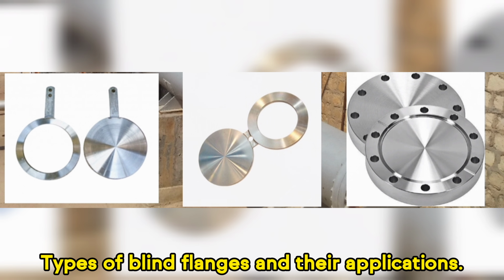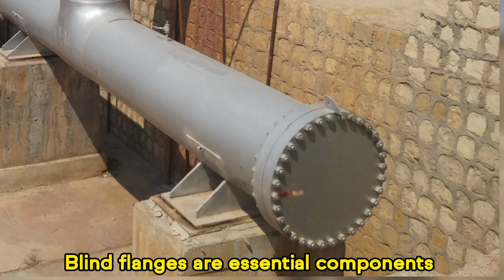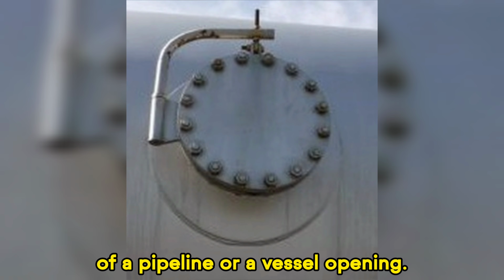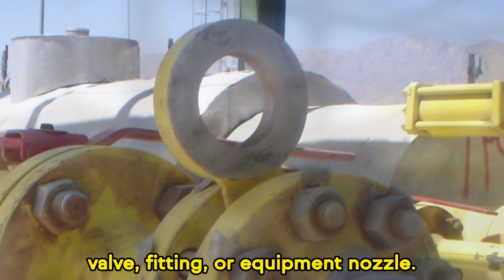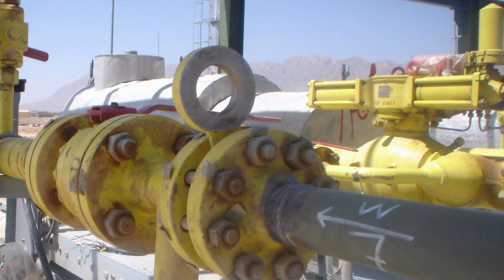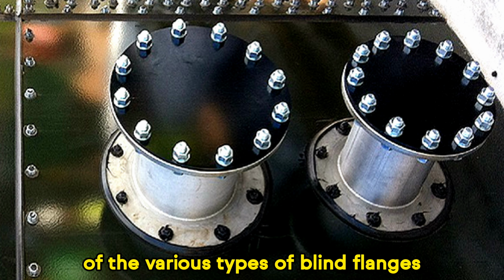Types of blind flanges and their applications. Blind flanges are essential components in piping systems used to block off a section of a pipeline or a vessel opening. They are solid discs used to cover or close the end of a pipe, valve, fitting, or equipment nozzle. Here's a detailed overview of the various types of blind flanges.